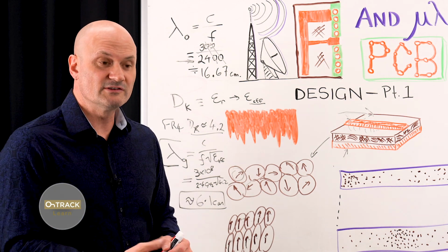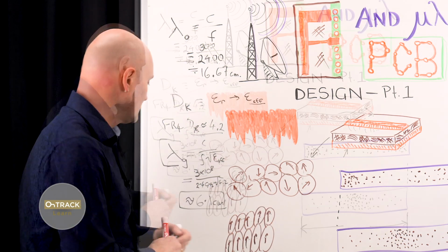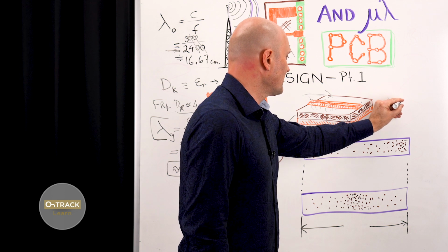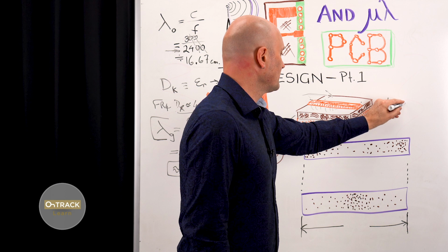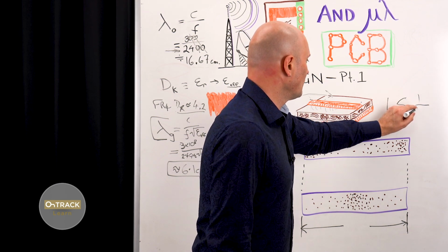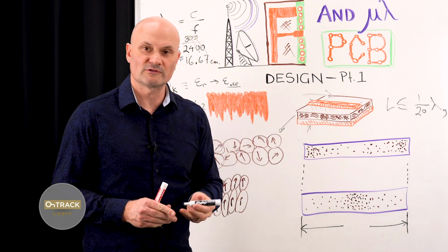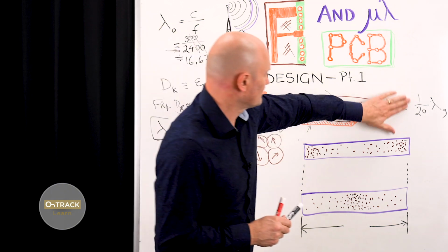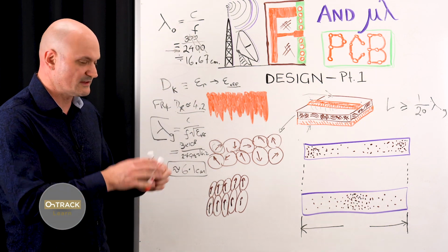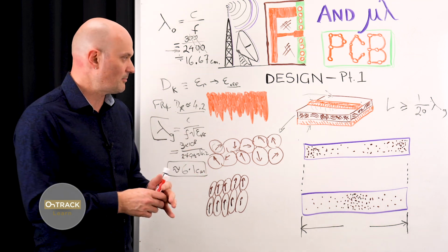And the general accepted industry standard, if any of you are electrical engineers, many of you are, you'll remember this from your transmission lines class and fields and waves. The general rule is when the length of an interconnect on a PCB is greater than or equal to 1/20th of the guide wavelength, no, it's greater, sorry. At that point, you're dealing with an RF or microwave design, because the length of the traces and features you're dealing with at that point have a profound impact on how the circuit actually operates.